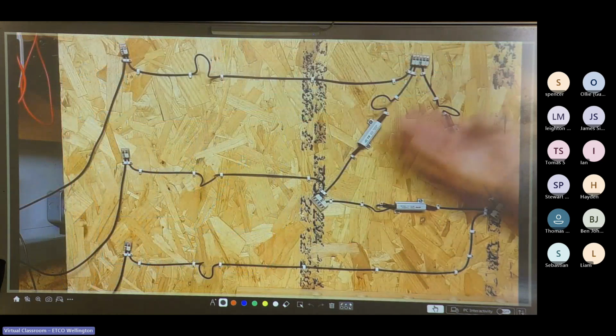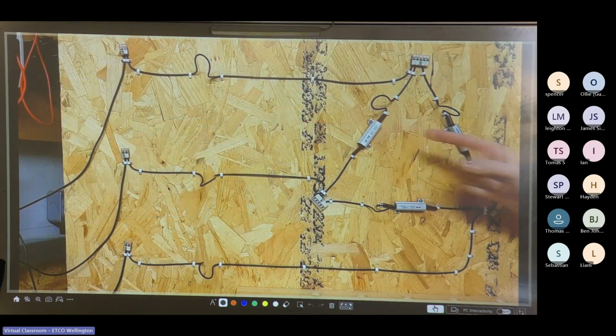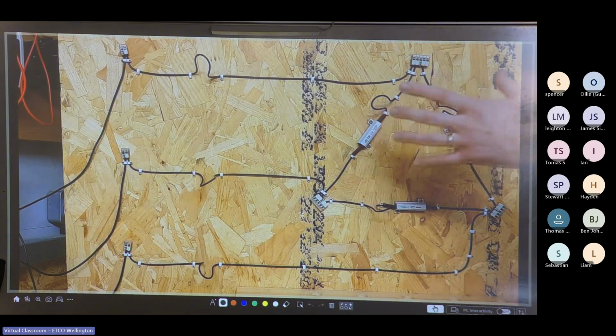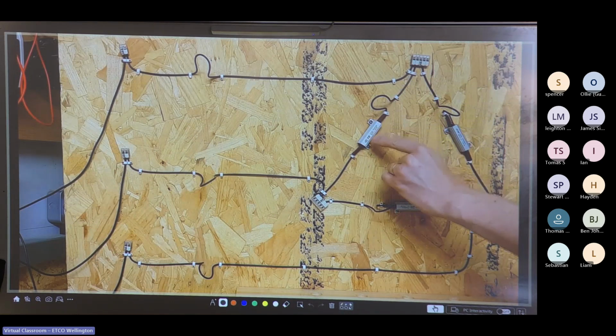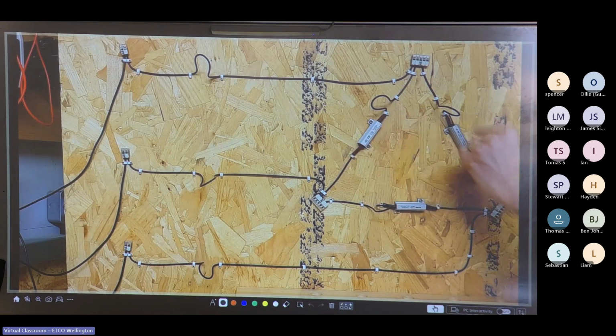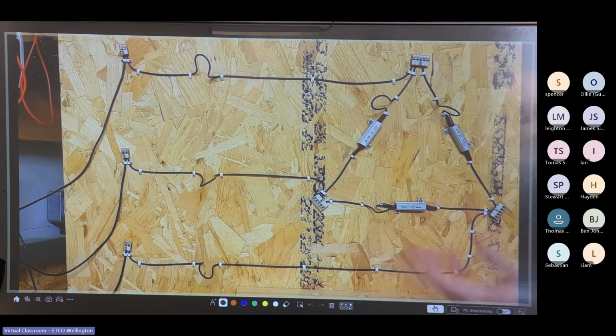On our simulated three-phase load here, you can see we've got three loads. Again, these loads can be used to represent perhaps the three windings of a motor. Obviously, there's some inductive effect to take care of there, but we'll look at that in a later video. And what makes this a delta connection is that if we look at each individual load, you can see it's got two connections. Traditionally, we think of those as being the line and neutral connections.